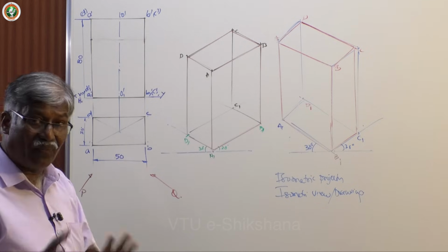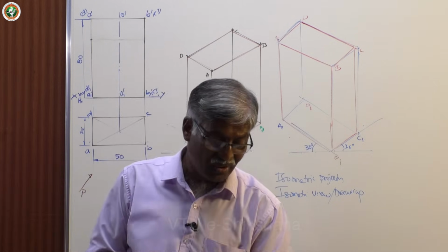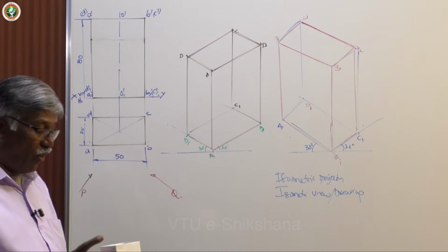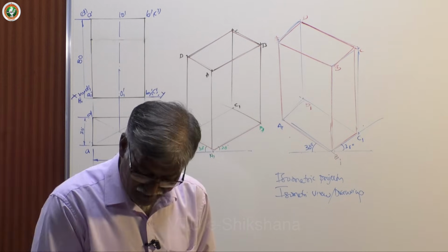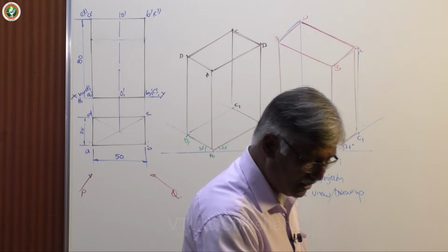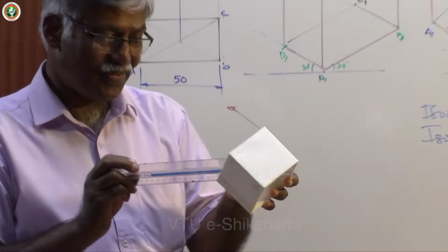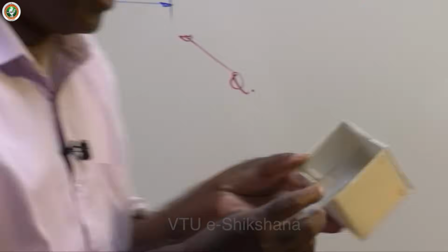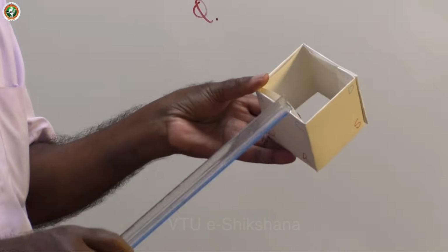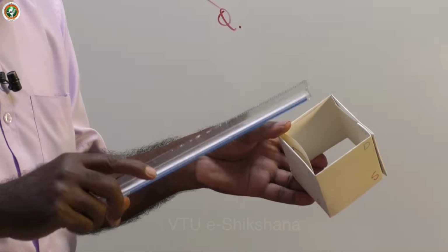Now, to explain this, I will take up a simple solid which we already worked out in projection of solids. In a particular problem we had the solid diagonal parallel to HP and perpendicular to VP. Let me keep it like this. This is the solid diagonal, joining the top corner with the opposite base corner, or body diagonal.